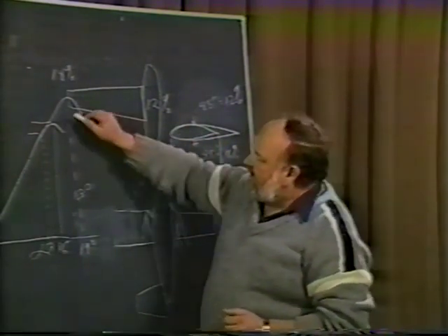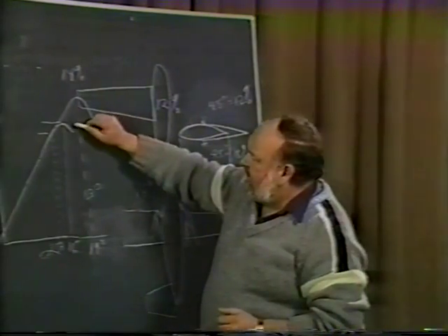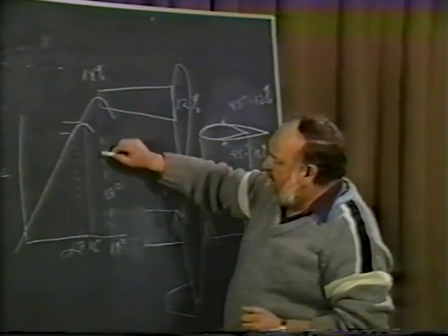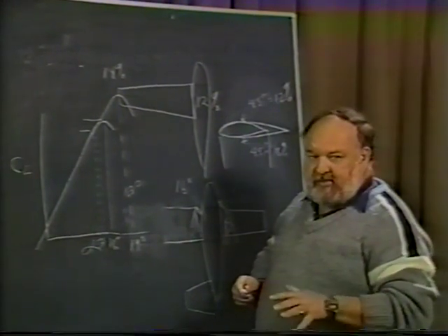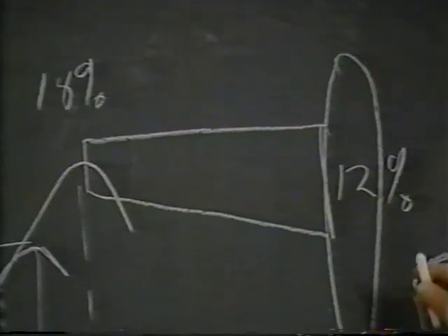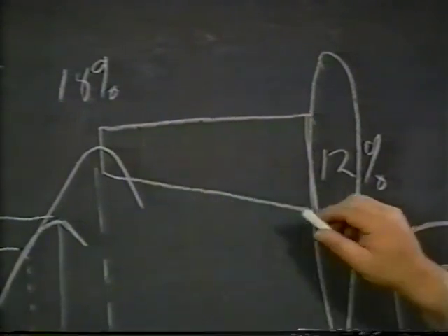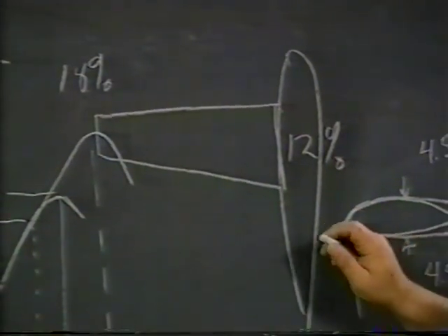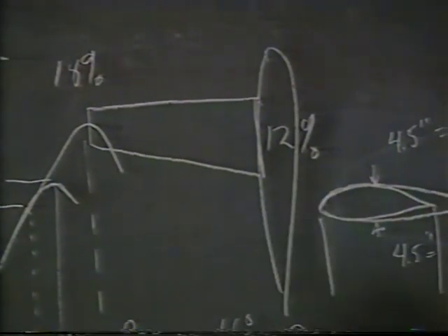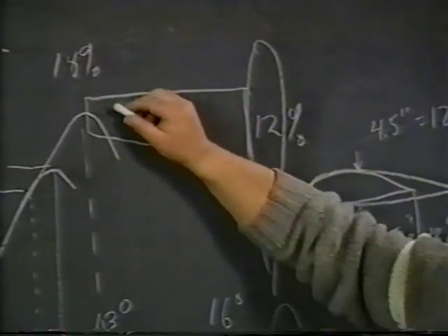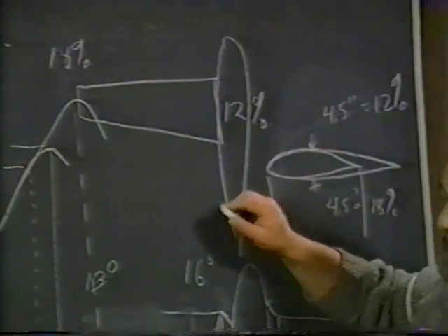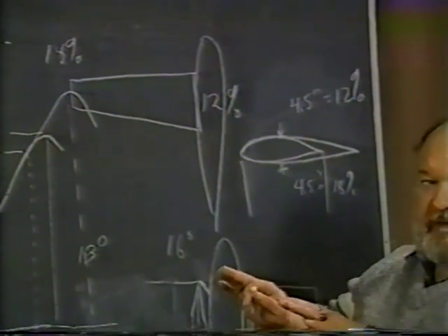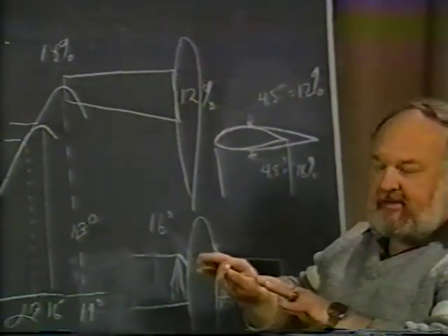But being a relatively thicker percentage airfoil section with a relatively larger airfoil leading edge radius to it, we ended up with a real nice lift coefficient. Our lift coefficient went higher at the tip, and it was 3 degrees later than what the inboard section would stall. What does this mean? Well, it means that not only do we have this tapered wing section, and that we have this excellent stall pattern, which because the outboard section is going to stall 3 degrees later than the inboard section, it means that the pilot can pull the airplane up, get into a stall, have it sit there and buffet.